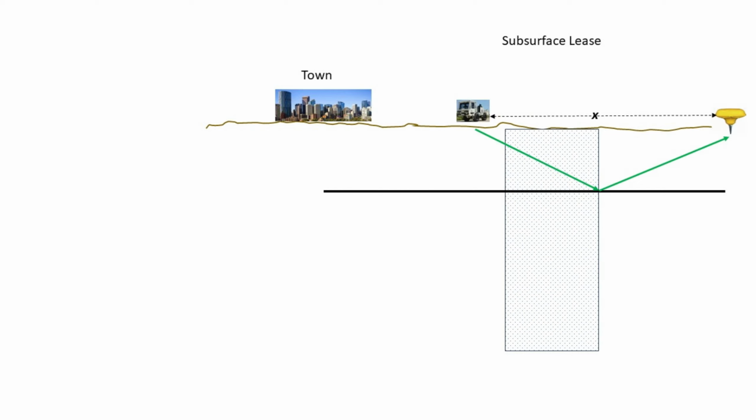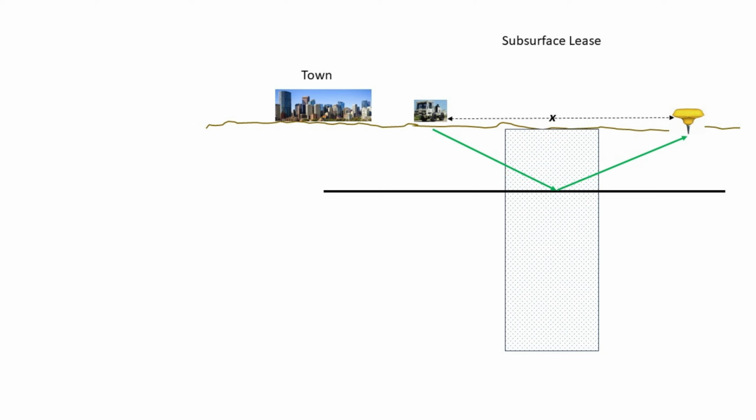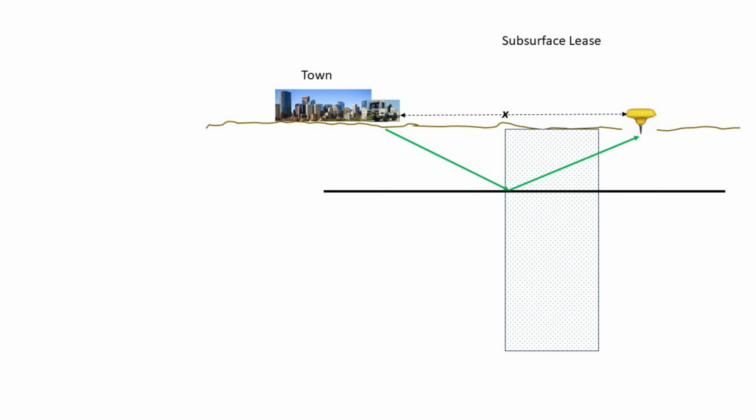Now typically you can have sources and receivers, and you can transpose them and have them replace each other. But in this case, the whole area on the right hand side was very wet and we could not get our sources over there. So we were limited to the other option like this for the recording of this horizon. To record that horizon, we would continue moving with our same geometry and move across until we got right up to town, but we'd managed to successfully image that whole horizon.